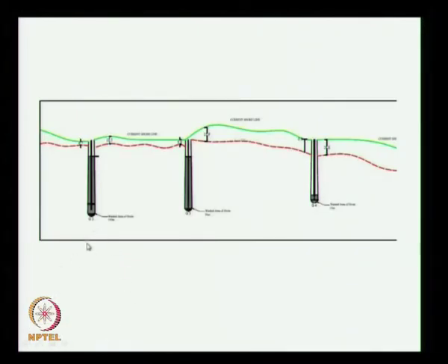This slide shows the groins built and the red line shows the shoreline when the groins have been started, that is in December 2011 this was the shoreline. Now December 2012 this is our shoreline, about 20 to 40 meters the shoreline has got eroded.